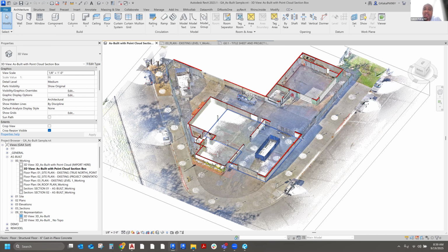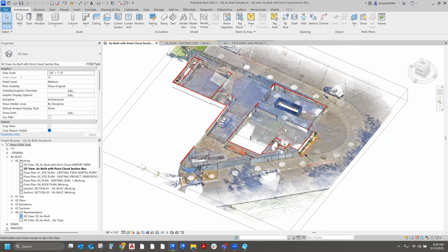Because as I said, drawings change through construction. A lot of things change, and then nobody changes the plans, because everything gets captured by the contractor. So then you need a new set of drawings at the very end, which is what as-builts are. Plus, a lot of property owners build things that aren't permitted, so there's no record of them.